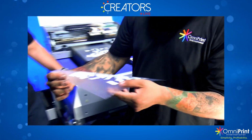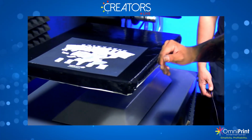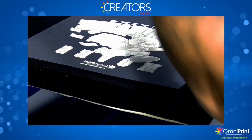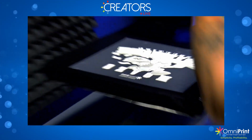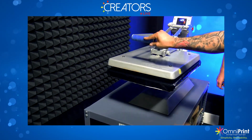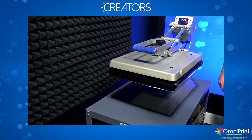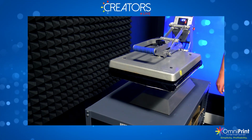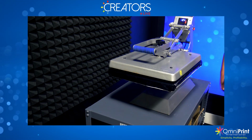Now, before we press it, we do have to melt this glue down. What I did here on the heat press is I actually removed my cover. One of the reasons I remove it is that after some time the cover gets stretched and dangles down. When I hover right now, I don't want that cover touching my film. So I removed it, and I put all the pressure down, so when I come down and lock it in, it hovers over the print. Right now it's not touching it. It's about an inch away, and you want to do this for 2 minutes. You're just going to let it cook there for 2 minutes. It's basically melting the glue, activating the glue, and we'll be able to press it immediately right after.